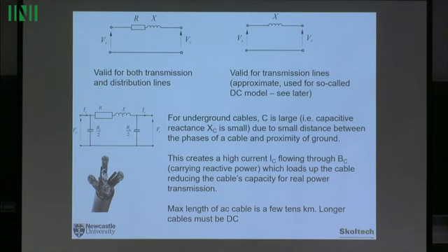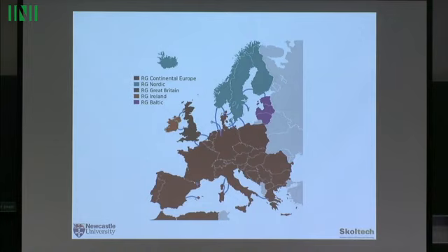And this is the reason why, in Europe, we've mentioned underground cables. The connections, those blue ones, are connections between countries. So there are cables running underwater, undersea, and for that reason, if they were AC, they would be loaded by reactive power. There will be high capacitive current, useless. So that's why those cables have to be DC. Not to do with the water. No, basically they run underground. Put it underneath a mountain. It's the same thing. It's just the question that the ground is around it. It's very small distances, right?